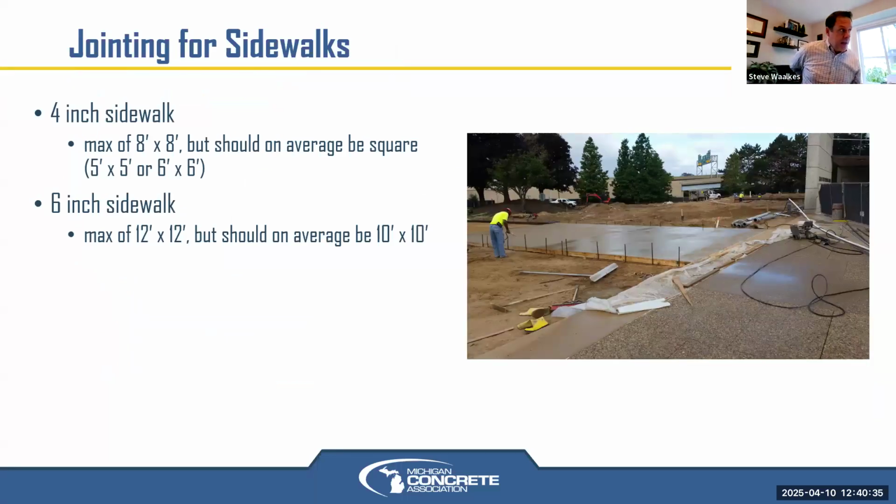On sidewalks, I mentioned 6-inch sidewalks. We've seen some, especially in areas where they're going to have some heavier snow maintenance equipment. If it's not just going to be a small little pickup, it may have a pickup with a salt spreader on the back, so it may have some heavier weights. They're worried about a 4-inch sidewalk and having snow equipment being at the heaviest loading situation. They might bump it up to 5 or 6 inches, and then you can do your full 10-foot by 10-foot slabs.